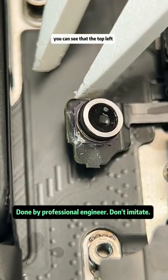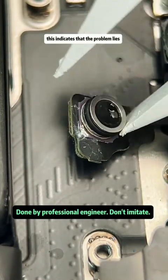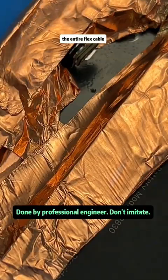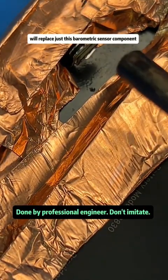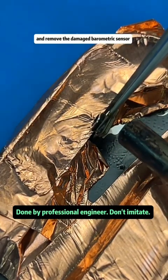You can see that the top left barometric sensor has turned white and corroded. This indicates that the problem lies with the barometric sensor. Here we could choose to replace the entire flex cable or replace just this barometric sensor component. We protected other parts and used a heat gun to heat up and remove the damaged barometric sensor.